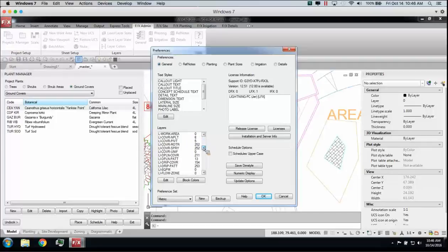And I say a lot, but not too crazy. I'm just going to show, like in here is where it sure looks like a lot. We used to have all of our irrigation heads just simply placed on li-head. Now you can see, obviously, it's splaying out, so turf rotors are placed on this layer. Now you're certainly welcome to rename both of these layers to both be the same if you want all of your rotors on the same layer, but obviously that's going to be very helpful for freezing layers and isolating things.